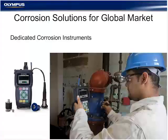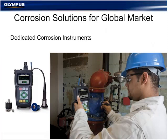So, Coleman had mentioned earlier, if we start looking at these solutions and start from the bottom here, a dedicated corrosion instrument is one of the lower cost single point type instruments that can be used. And this is very much what Coleman is emulating with the flaw detector that he's just done a demonstration on. These products are very accurate at reading corrosion. They are a single point measurement unit, however, and they can often be very simple to use. The waveform on some of these instruments can be optional, so in some cases you're just looking at the thickness reading and only the thickness reading.